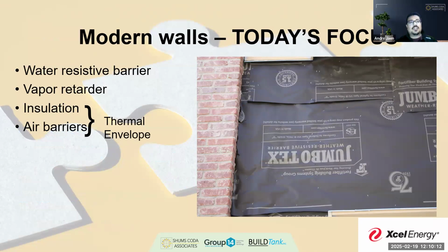So, with our insulation and our air barriers, one of the most important things to know is that they create the thermal envelope. You're seeing more and more code sections clearly tell you that it's not only where there's insulation that's going to break up things like having a mechanical room inside of your house, right? And you want to isolate that thermally, or your ducting, right?